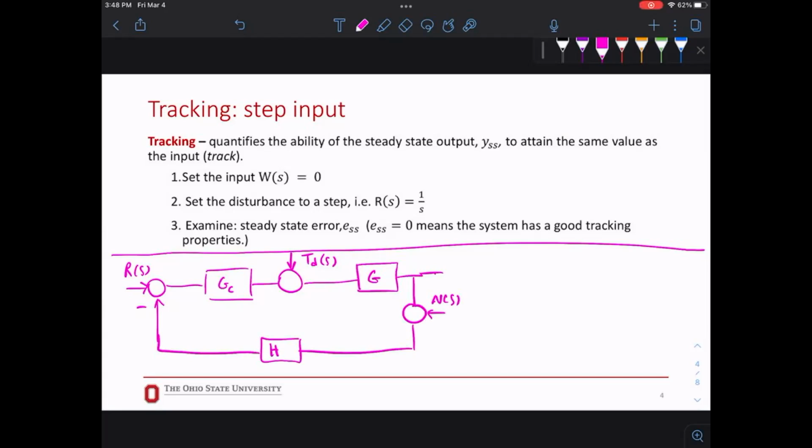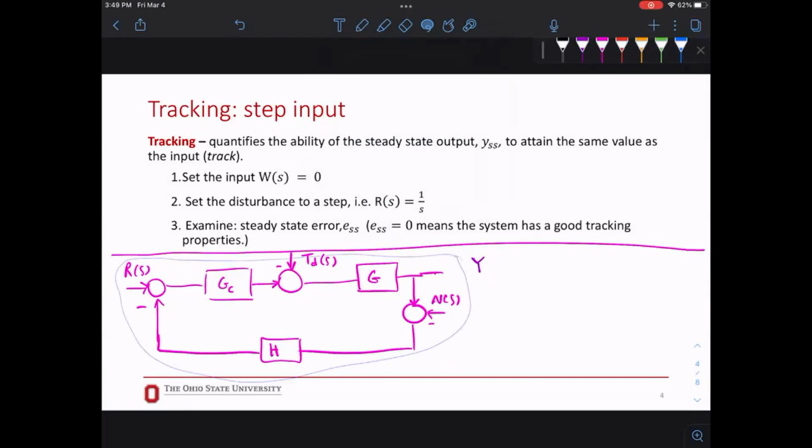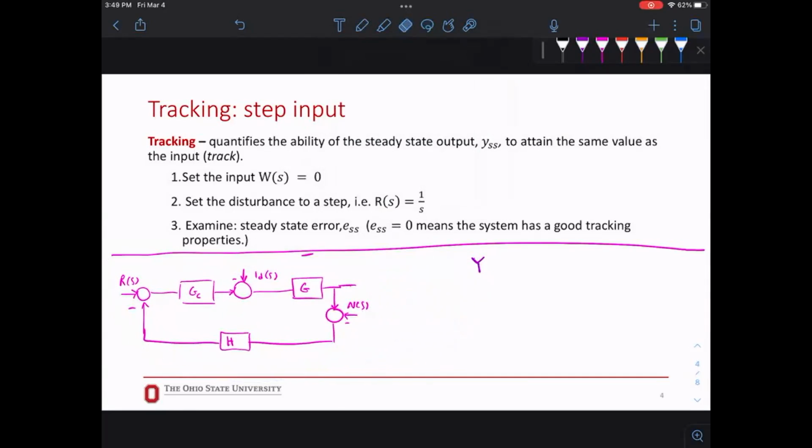And then this would be your H, right? Now, for finding the transfer function, you have to find your output Y. Your transfer function is your output over input, right? Now, you don't have only one input, you have 3 inputs. So if we write the output in terms of input, I'm going to make this small to create myself some room. This is OCD right there in flesh for you. So you have to do some block diagram reduction and some superposition here. I'm just going to write the final solution, but it will make sense when you see it.